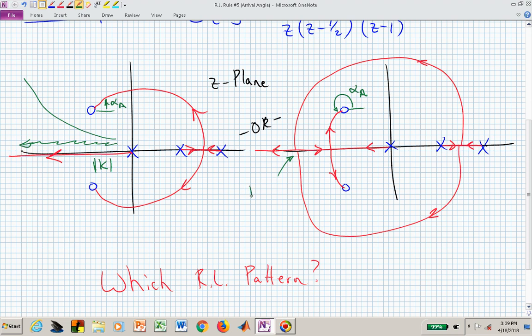This is now going to be a relative min for K, and here is a breakaway, so this would now be a relative max. So if we plotted K, K would be very big here, but then it would be decreasing at that point, and then it might be increasing there, but we know that it goes to 0 at the origin.